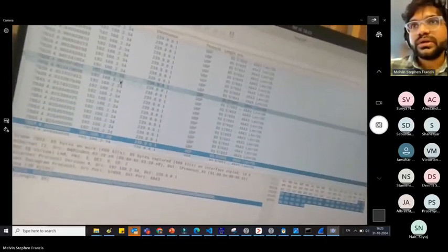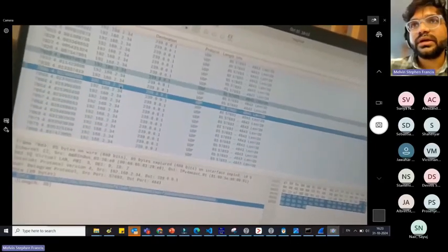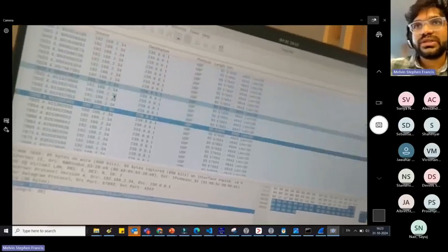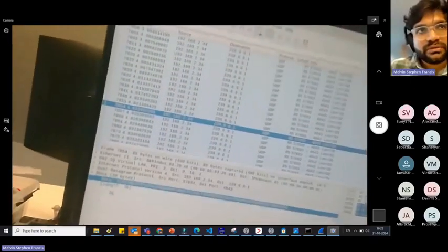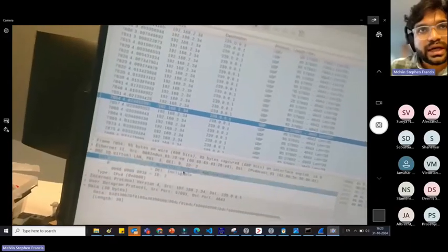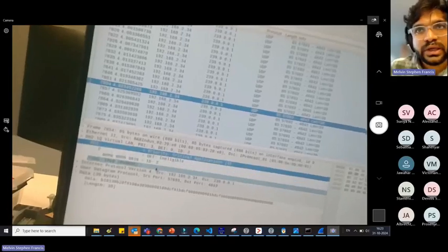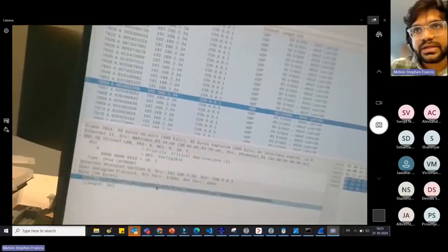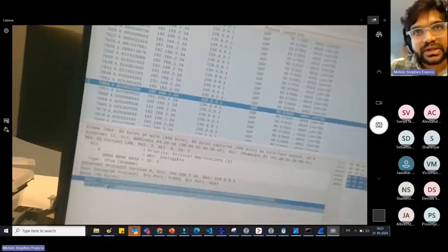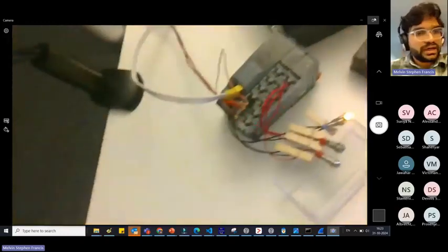I just filtered out the wrong packet, but this particular PC does not have a filter for us. At least you can see this VLAN ID that we are sending. So the critical application is sent at priority code point 3 and VLAN ID 2, and we are sending the PubSub data packed as a UDP packet here. So this is what is happening right now.